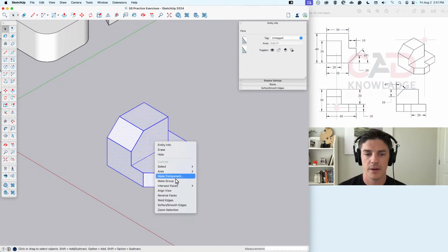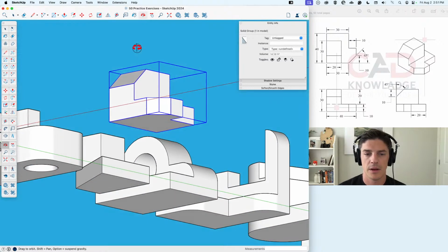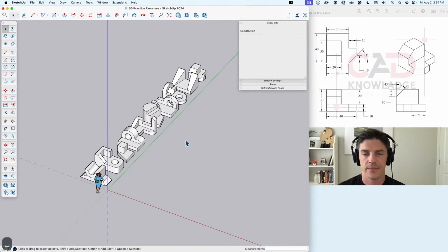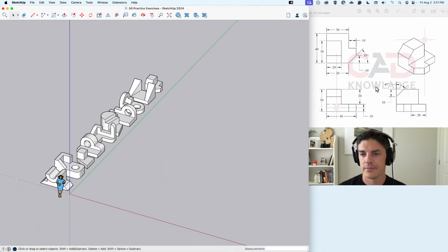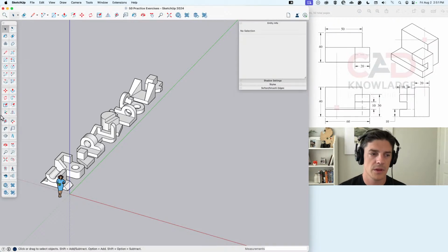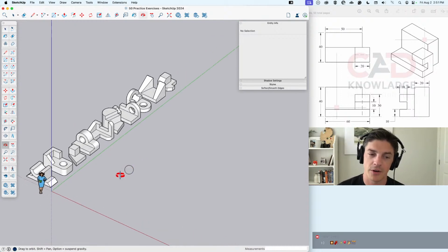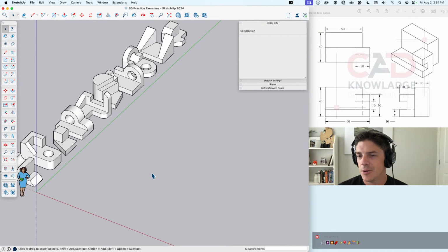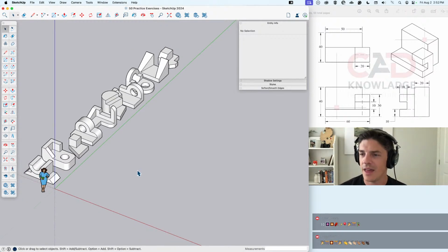I think ultimately we say this to more intermediate advanced users, like use your shortcuts. But when you're first learning, it's really important to have that large tool set up because when you hover over an icon, it gives you what the shortcut is. So even though you need the tool in the beginning, you can start almost mentally mapping the keyboard, the default ones anyway, in your head. They're pretty simple, like L for line, right? Should be intuitive. P for pencil. Oh wait, push pull. That one always messed me up when I first started. I was like, it looks just like a pencil, but then no, that's line. P is push pull. That we can definitely agree on.